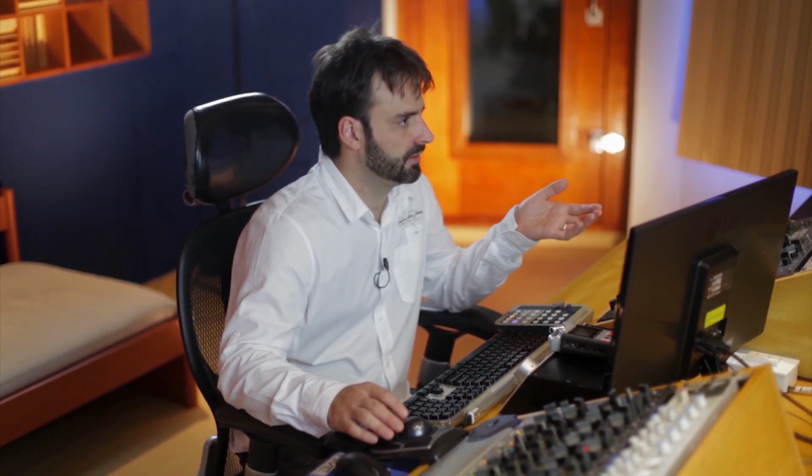The front of the room is acoustically dead in order to lessen the first reflections, avoid any unwanted effect, and allow the engineer to hear the effect caused by the first reflections from the previously recorded audio coming from the recording room. Since an anechoic environment should be avoided, the back of the room was responsible for generating the desired reflections.